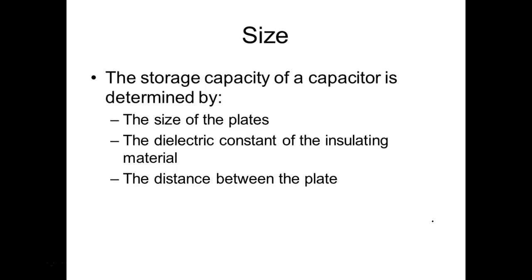I'll show you a video where they're popping them directly. And of course, the amount of current flow we get through these things is determined by the voltage. So these things have what we call a working voltage. If you exceed that working voltage, then you're going to have a lot of current flow through the dielectric, and you're going to push that current through a voltage, and these things will pop on you, right? You understand that?